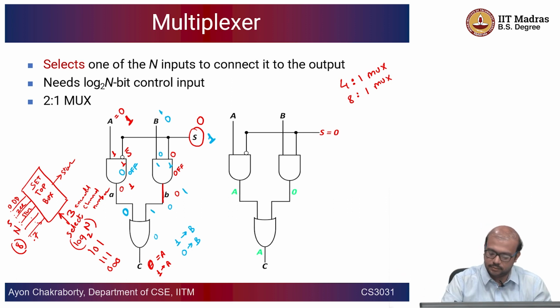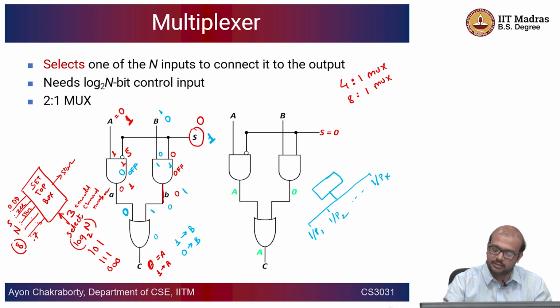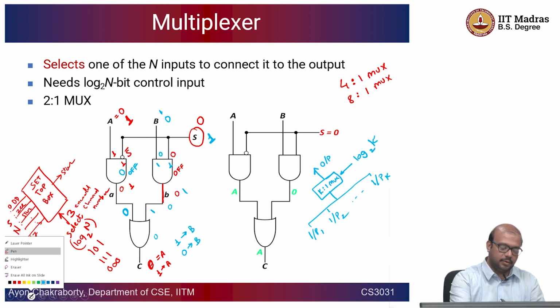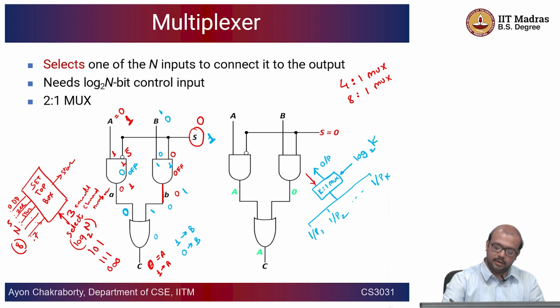Okay. So, just to show you, this could be input number 1, input number 2, these could be devices that will send you data, right, input number k, and this entire set of inputs could go to a mux, right. So, a k-to-1 mux, right, and you have the output ready and this output is basically one of the k inputs, and here the number of selection lines is log k to the base 2. Okay. Now, you can control which device you want to talk to, or you want to read or write from. Okay. So, writing requires the other direction, called a demultiplexer, like a decoder. If you want the other way around, that is also possible, but that is a demux. Okay.